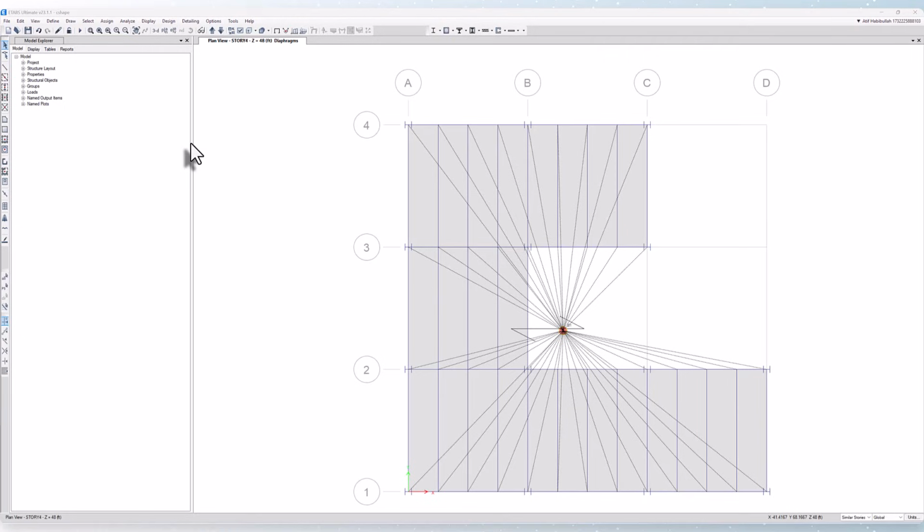But first, let's discuss rigid versus semi-rigid diaphragms. So as stated before, rigid diaphragms have infinite in-plane stiffness properties, and therefore they never exhibit membrane deformation nor report the associated forces. But when a semi-rigid diaphragm is used, it simulates actual in-plane stiffness properties and behavior.